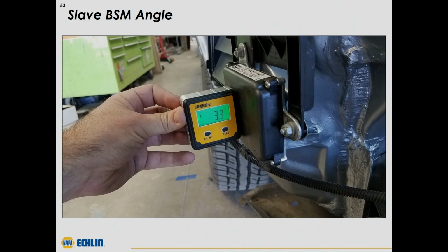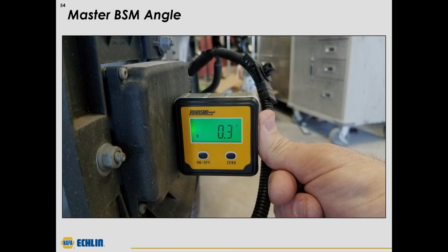There's not really a lot of specs on this situation. Well, we have a right side of the vehicle that is going to be perfectly okay. So how about we go to the left side of the vehicle, measure some of our inspections, and see what we get on the right side. So we go to the left side first, which is our problematic side, and we measure 3.3 degrees on that radar. Going to the right side of the vehicle, we're at 0.3 degrees. So it looks like we've got a 3-degree difference somehow between these blind spot modules, and we've got to figure out why there's a difference.